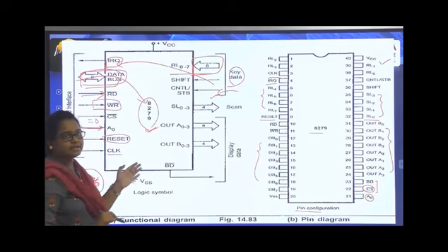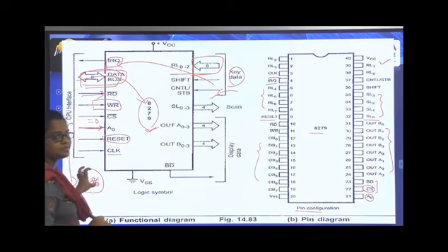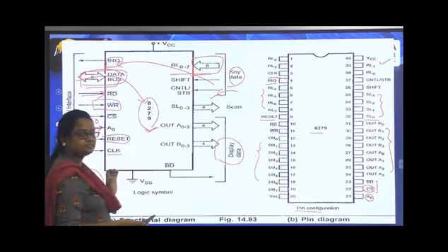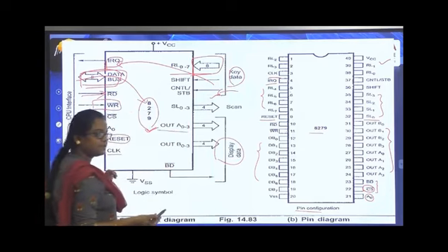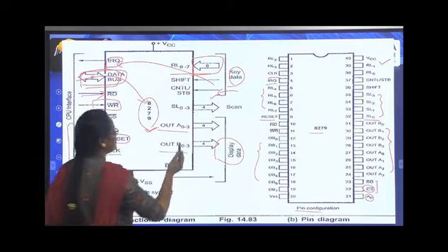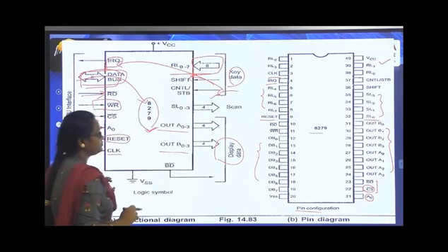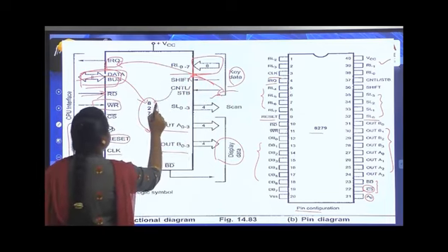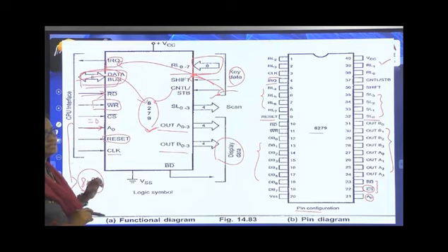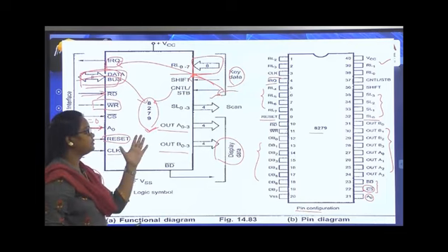The operation executed by the 8086 microprocessor is given at this stage as display data, that means outputs A0 to A3 and B0 to B3. Whatever input we have pressed, the 8279 informs the 8086 microprocessor using the data bus and IRQ commands, the 8086 executes what the user gave, and that output is given to the 8279.